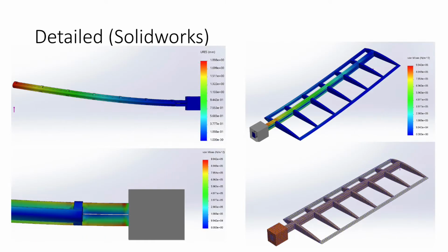To have a more detailed illustration of the wing, we used SolidWorks to assemble the different components together and subjected it to stress tests. These were far more in-depth than the Excel, as the fine mesh we used solved the stresses and showed the distribution throughout the beam. The highest stress was at the root.